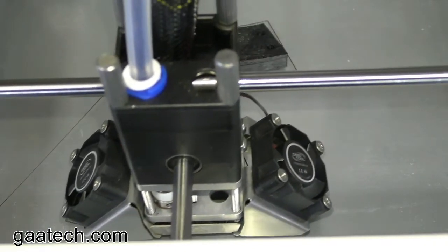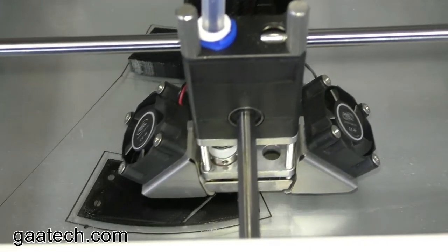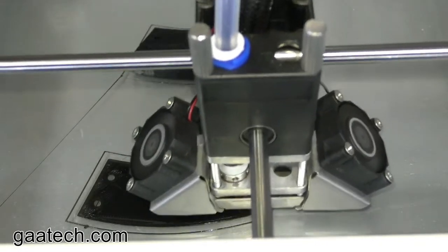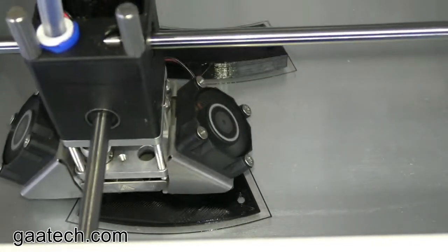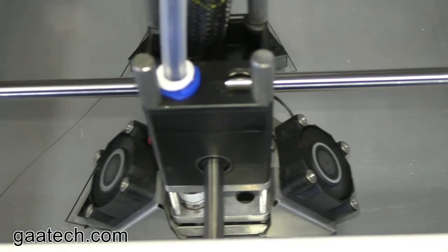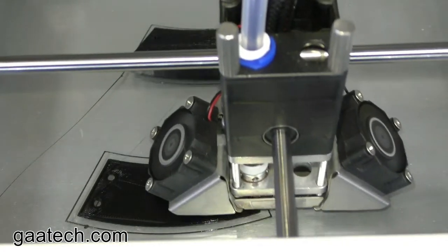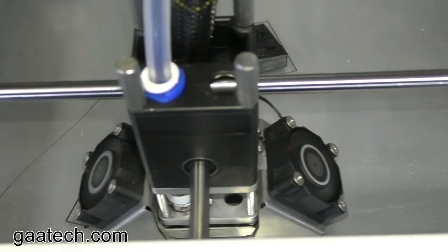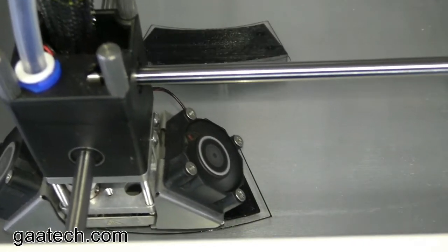So there it's done the far side, now it's jumping back to the section that it missed. Now it'll whiz around the outside there. The fans have come on, so it's only done the base layer. And the reason the fans come on is to cool the filament to make sure each layer will stick to itself. So it's doing 2 passes around the outside and then 2 passes around the holes. And then it will jump back into infill the base layer, and that should be another solid layer.